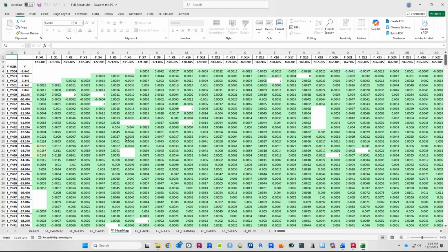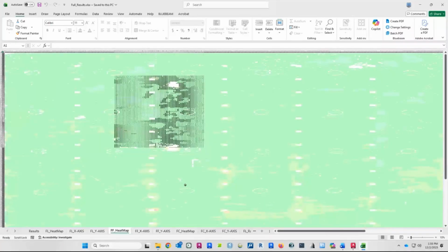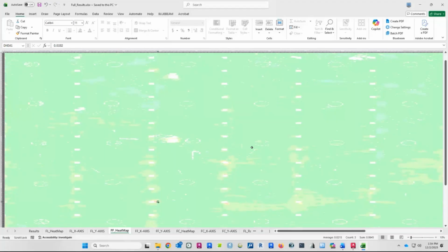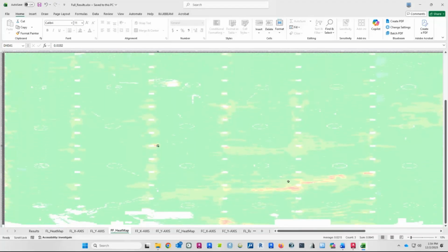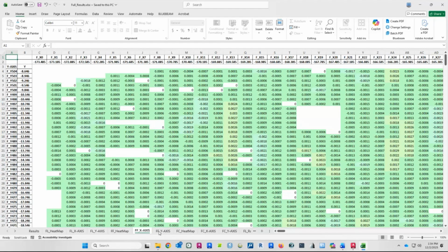So if we went to the floor flatness heat map here, you'll see, if I back out, the failures start getting colored as red and green or lighter green, and you'll start getting failures on this. And as you zoom in, because this is thousands and thousands of point measurements, you can see what those deviations are and also what their grid locations are. So you can get all the answers you need without ever opening up a CAD. If your team doesn't want to use CAD, they just want to use an Excel spreadsheet, all that information is embedded in here.